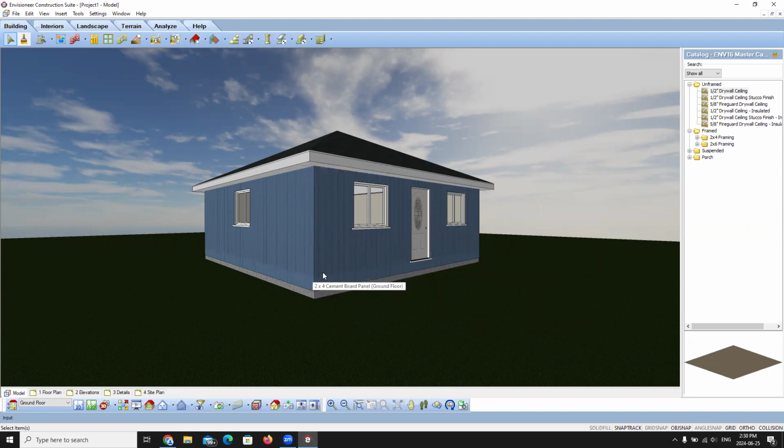And I can see that there is a bit of a transition from the bottom of the material to the top of the material. So we are seeing a bit of a seam here. I can again go back into the properties. Oops, sorry. Select all similar properties.